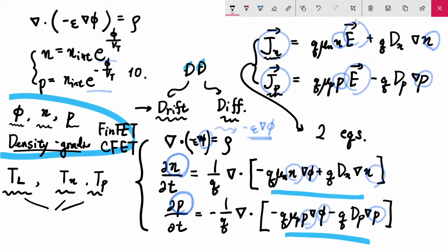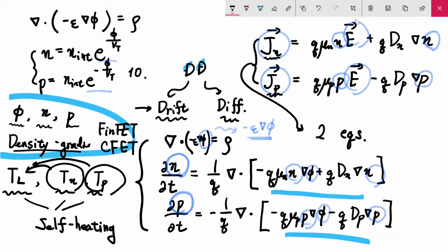Yes, you are right. That's a really good question. If we are talking about the self-heating case, and in many cases we are, then energy is usually stored in our electrons. So first, electrons or holes are heated. After that, that additional energy is dissipated to the lattice. So how can we transfer our energy stored in the electron system to the lattice system? That is what we call phonons. So that is the basic mechanism to deliver our energy from carriers to lattice.